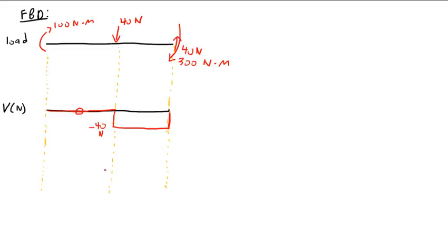Is that instantaneous, as in it's a vertical line going to 0? Yes, our forces here are instantaneous. That's why they're called discontinuities. We can have different types of discontinuities in equations. If they were asymptotes, they'd be going to infinity, but we typically don't deal with those in shear and moment diagrams. Typically, the discontinuities you have are vertical discontinuities.